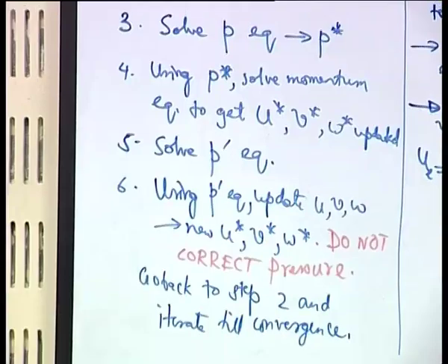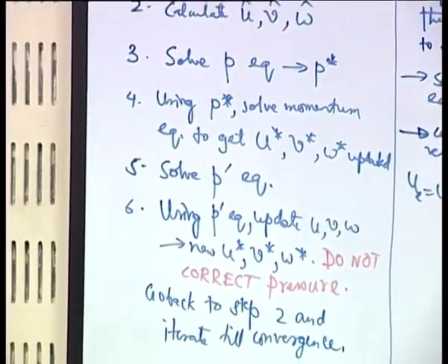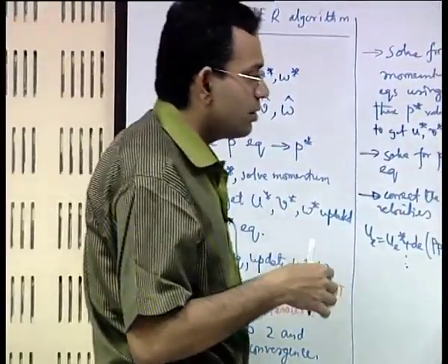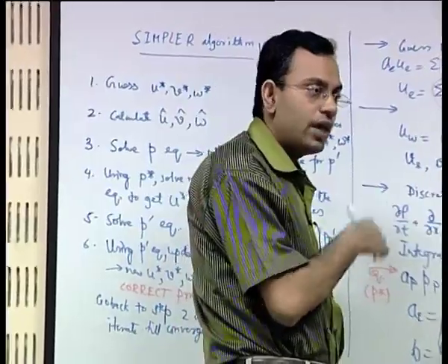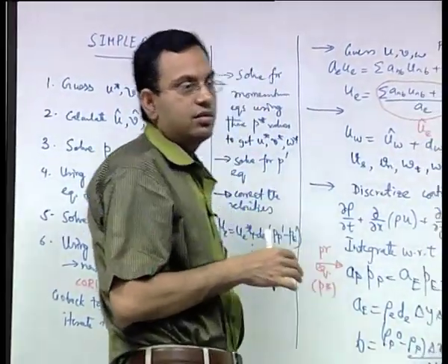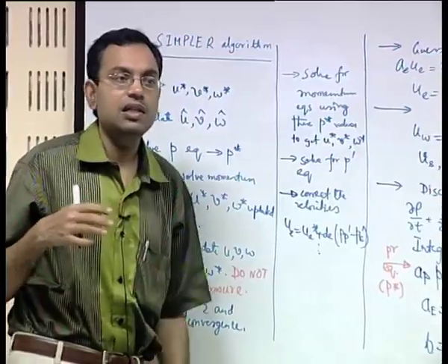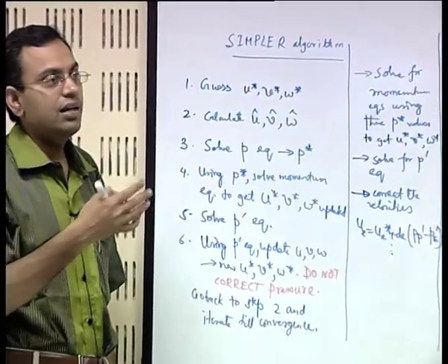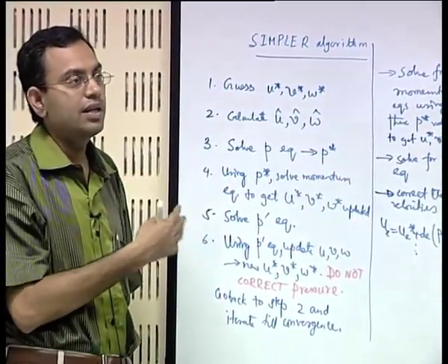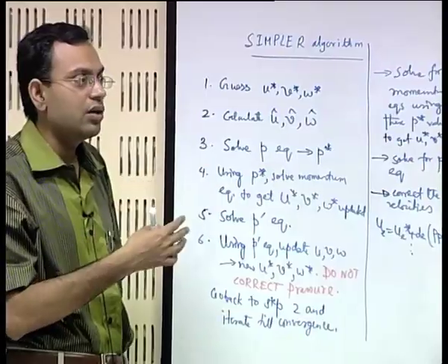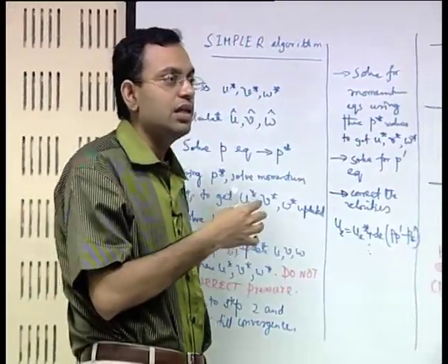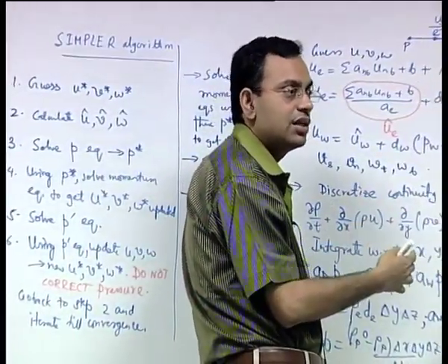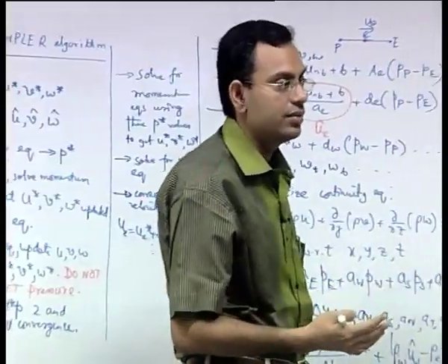So, this is the summary of the SIMPLER algorithm. Now, what are the advantages of the SIMPLER algorithm? We have already seen that since the pressure correction in the SIMPLE algorithm does not do a good job in correcting pressure, that adverse effect is now gone in the SIMPLER algorithm by virtue of the consideration that you no more use the pressure correction for correcting pressure, you solve the pressure directly.